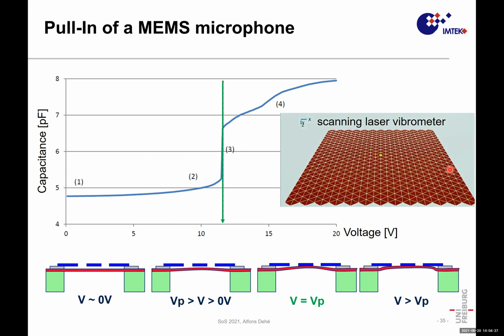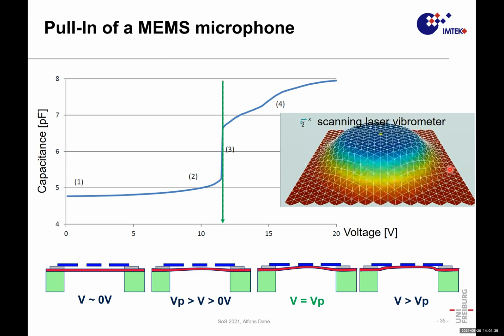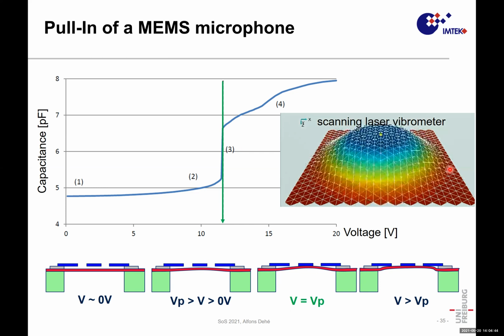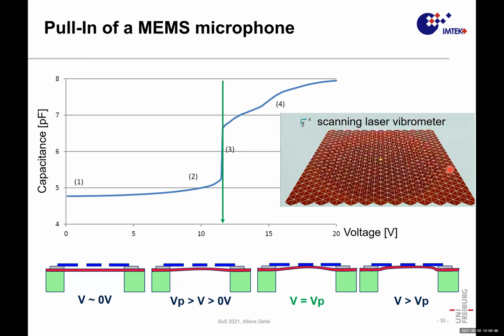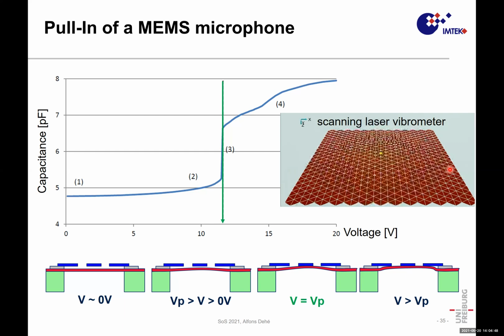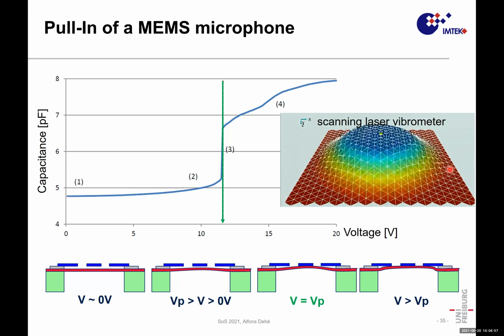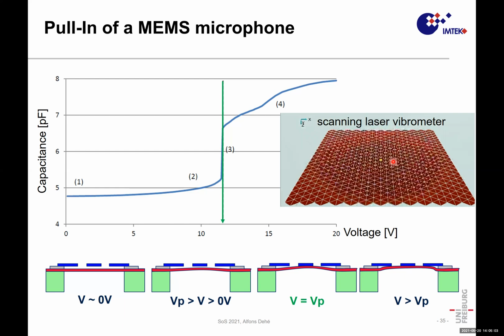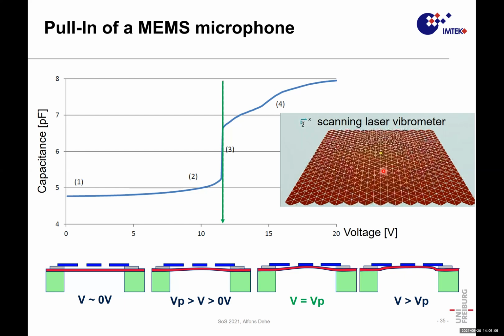This is an optical measurement of such a diaphragm. In this measurement, you see that we run up the voltage and now down again, and the diaphragm is moving. The backplate is transparent for this measurement, so you won't see it. I run it again. You see the voltage is increasing. Zack, now it is hitting and moving again, and now we reduce the voltage again, and it's getting free again. And now a little free oscillation of the rest of the diaphragm.